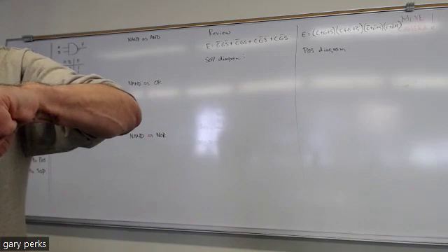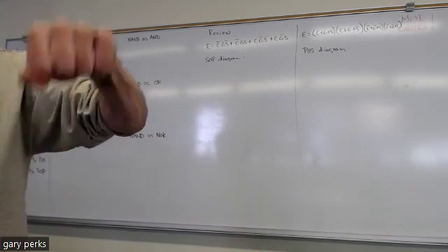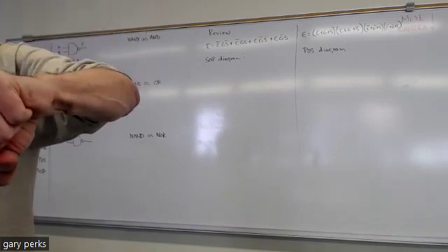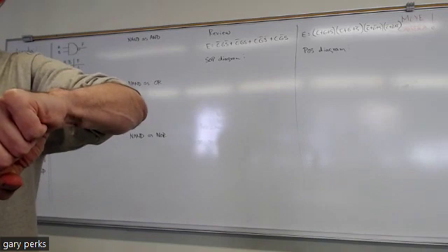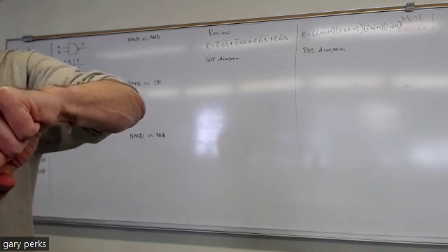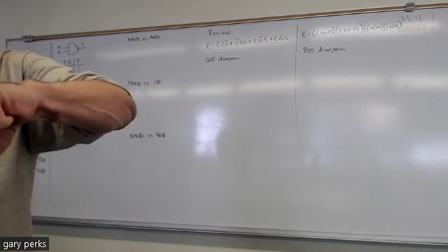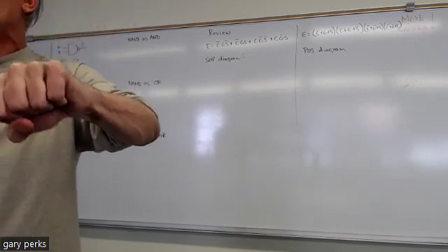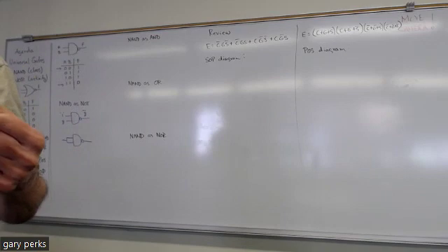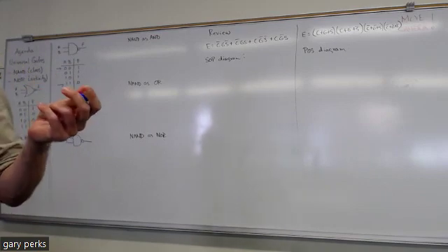What's the best case that's going to happen to your power supply? If you take one end of the power supply and connect it to the same node as ground of the power supply, you're shorting the power supply. So best case scenario is the fuse blows, worst case scenario is you burn something up.